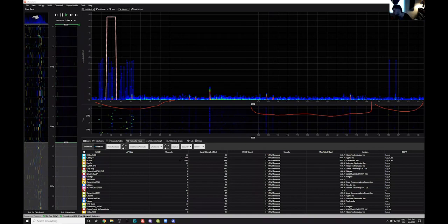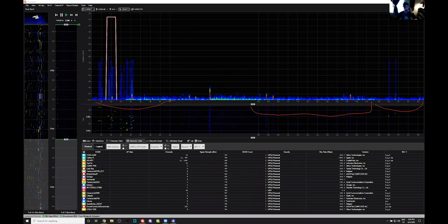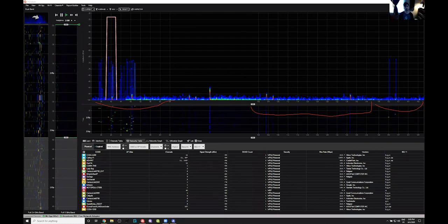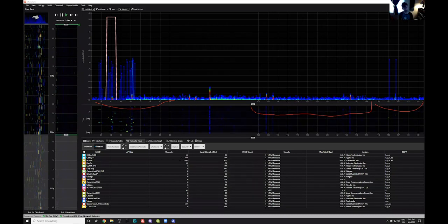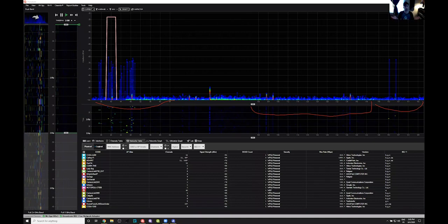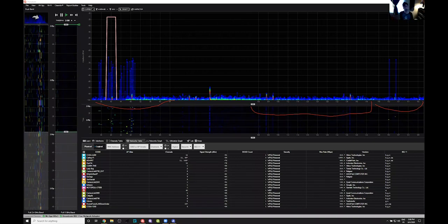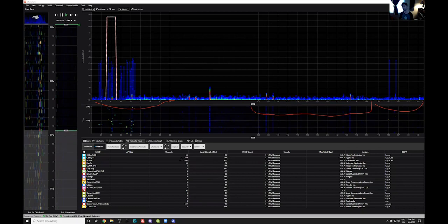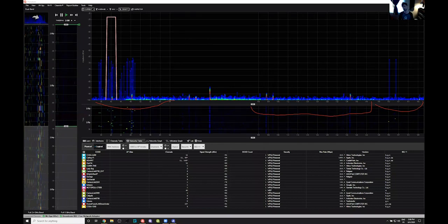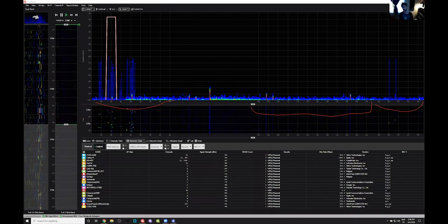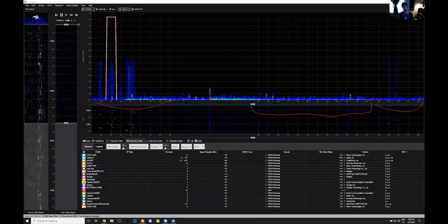Okay, so last question, Brian asked, omnidirectional antenna to use for 2.4 and 5 gigahertz, any recommendations? Yes, we use what's called the Alfa APA-M25. It's perfect, actually. It's RP-SMA connector. It's 2.4 and 5 gigahertz compatible. For you older customers, you would know that our previous omnidirectional antenna was only compatible in the 2.4 gigahertz range, but we've since moved on to the Alfa APA-M25, and that supports the 2.4 and the 5 gigahertz band. So that's the model we sell with the Chanalyzer Essential Bundle.